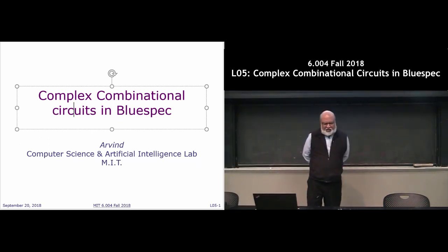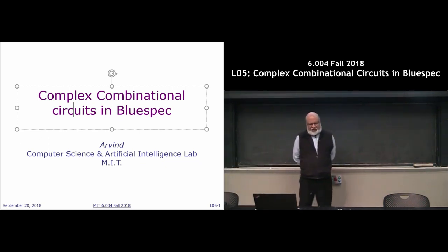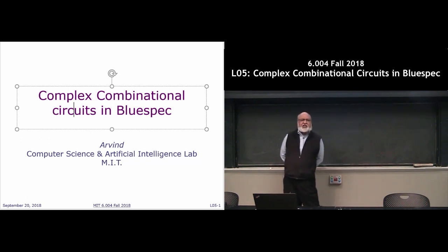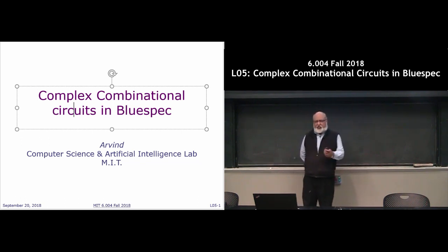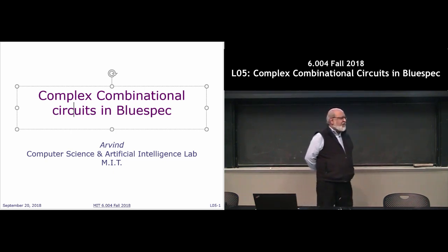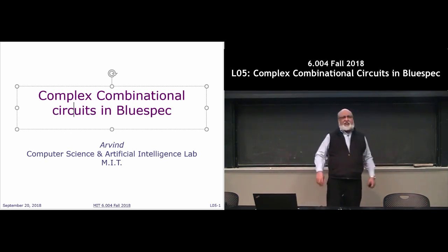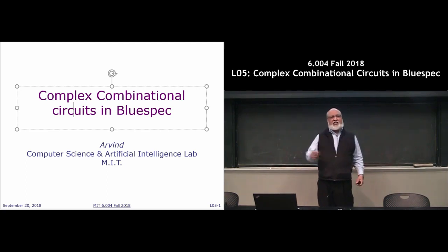I already said all this. Numeric type W on the right-hand side implicitly gets instantiated to 3 because of the way you wrote the code. And similarly, you could have done a 32-bit thing. You could have defined a 32-bit adder, and the right-hand side remains the same.